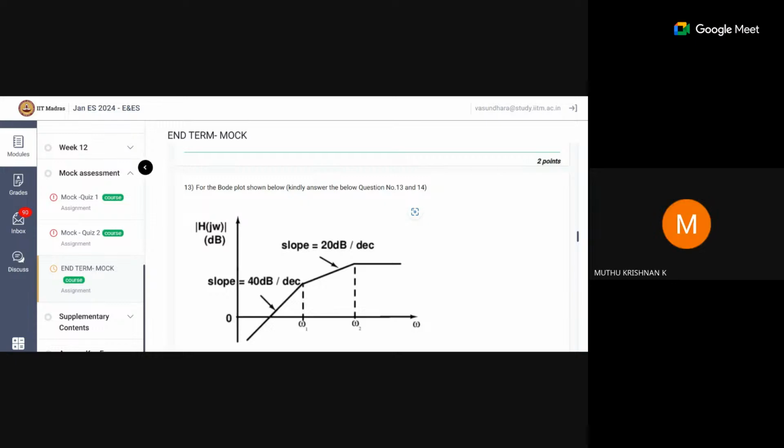Yes, K value is not required for finding the corner frequency. It will not affect it. The shape will be the same; the curve will shift upwards or downwards, depending upon whether k is increased or decreased, relatively.